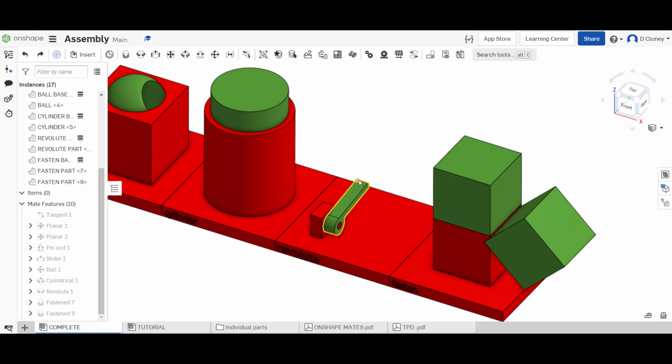If you have a look at this revolute, if I drag that, you will see it hits that surface and will not go any further, and if I pull it this way, it will not go any further that way. If you look at the one I've created in there, I've not applied those, so at the moment it will just spin around, it will not hit a certain limit. We're going to go through all these and have a go at creating those.